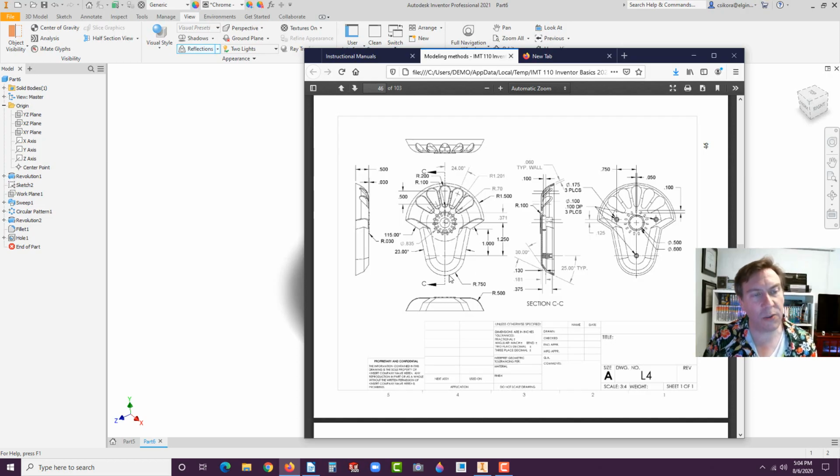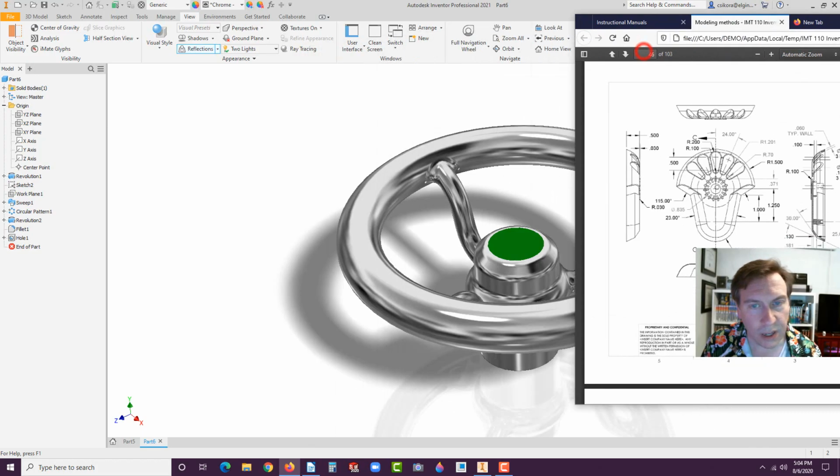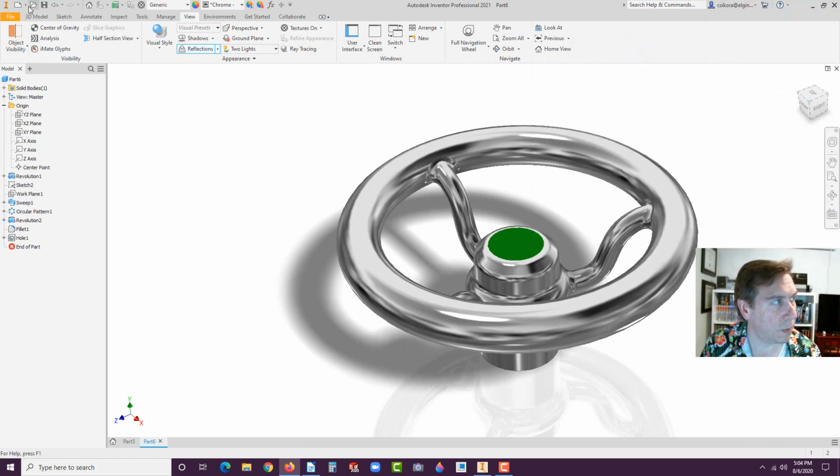Okay, so we could see this uses the same modeling theory that we saw with exercise 3 last week. So in this case, it's a radius of 0.75 at the bottom. It's tangent on those edges. And then we have 23-degree angles off there, and then 115-degree angle off of that. And then we have a dome over the top of 1.5. And the distance between centers is 1.25, and distance between that corner and the bottom center is 1 inch. So I'm going to drag this over, and we'll build that right now.